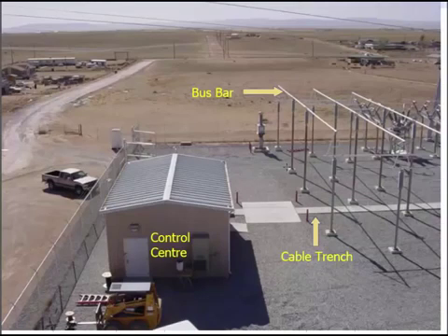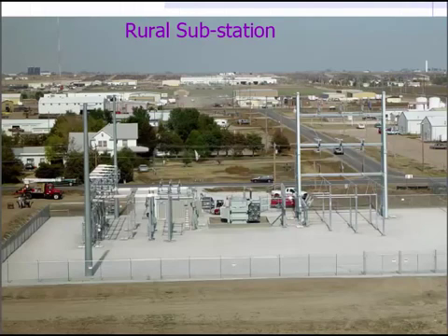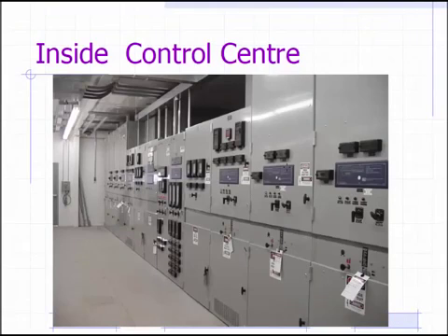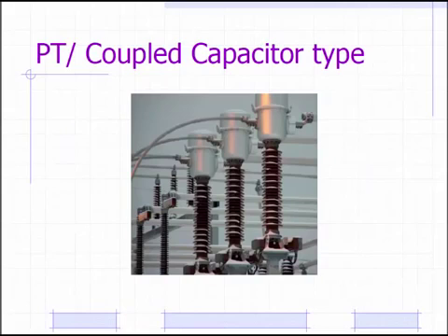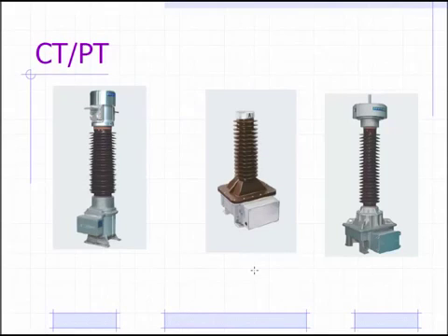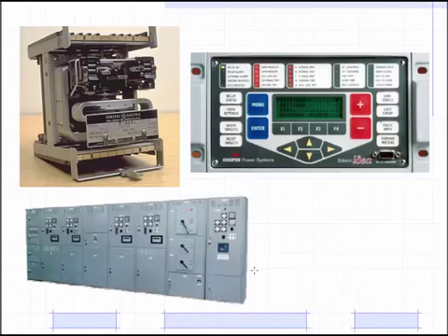All right, just nice pictures of different components that we might see in a substation. This is metal clad switchgear, so there could be breakers down in the bottom of these cabinets. CTs and PTs, we're going to spend quite a bit of time with CTs, PTs, and relays. CT stands for current transformer, PT stands for potential transformer, and these are what connect controls, meters and relays, little things, to big power system type things. There's some pictures of relays there.